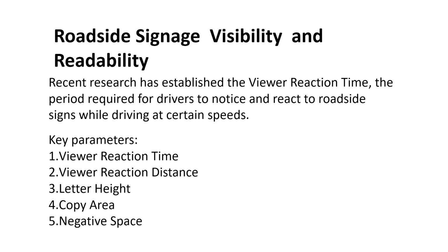Now, roadside signage visibility and readability. What is the most important thing in this? Recent researchers have established the viewer reaction time, the period required for drivers to notice and react to the roadside signs while driving at a certain speed, alongside factors such as letter height, message complexity and negative space.